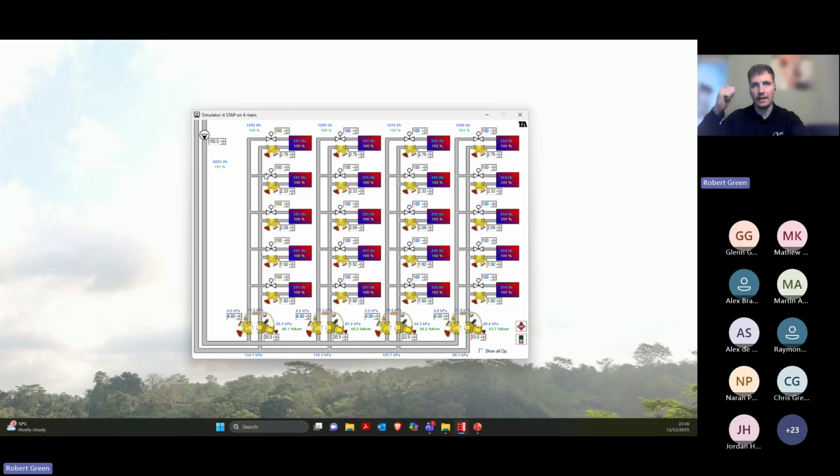So you could say, yeah, fantastic. I have achieved design conditions. I could walk away at this point. But what I have not done is I haven't optimized my system. So the first thing I want to do is I want to now force, and this may seem a bit backwards, but I want to force my pump to the minimum speed. So we're going to now drop it, and we're going to drop all the way down to, let's go all the way down to, I don't know, 70 kilopascals. Let's say that was the minimum speed of that pump.